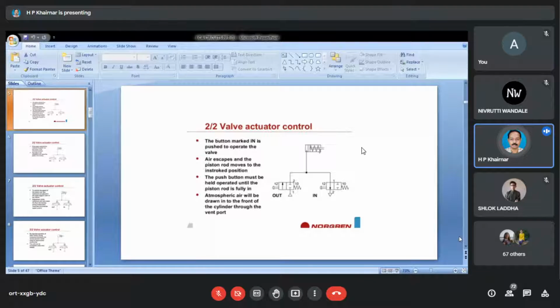See, I already told you that these systems work in some range, that is 3 bar to 8 bar. Sometimes if you are exceeding that pressure unknowingly, then the entire circuit will explode. Now suppose in our lab, I don't know whether you have visited the heat transfer lab, because for the last 2 years your batches have not been there. But there is one compressor in the heat transfer lab. Its capacity is, I think, 12 to 15 bar. So from there we have taken this pneumatic connection in the measurement lab on the first floor. So sometimes the pressure may exceed well above 8 bar.